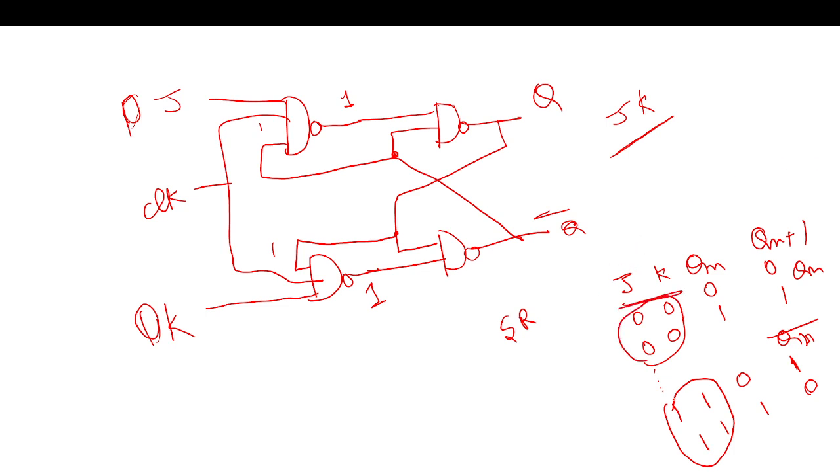And as it is in toggle state, say I'm taking this as a positive level latch. Here my output is set to 1. After the delay, that 1 is fed back and it toggles again, so it will keep toggling in this level.